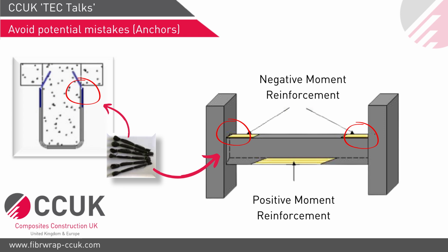But again, if you use these anchors, drill a hole between the beam and slab junction, put these anchors diagonally like that, they provide a similar effect as in closed. So this is the diagram shown on the left, yeah? Yes, it is.